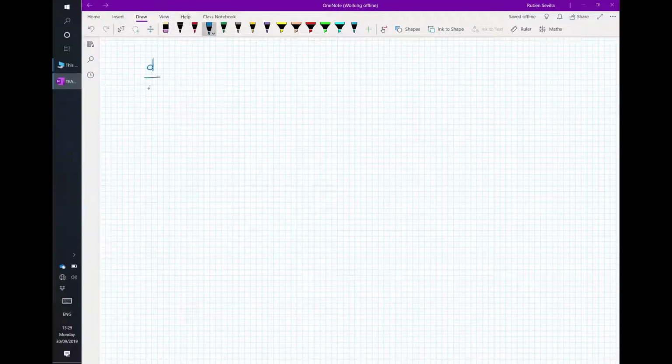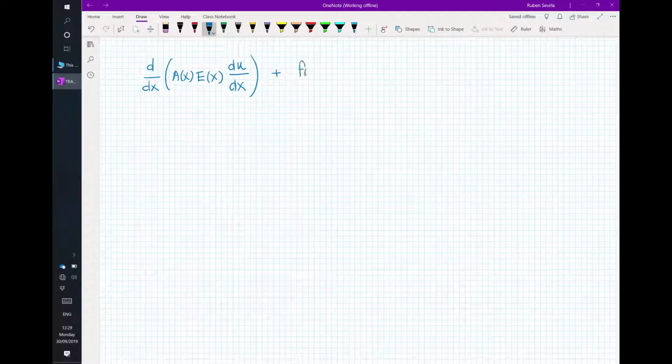So that's our equilibrium equation. And if I introduce the expression of the stress, which is Young modulus multiplied by strain, this is the actual equation of equilibrium, okay? Here what you have is epsilon, and here what you have is stress, right?